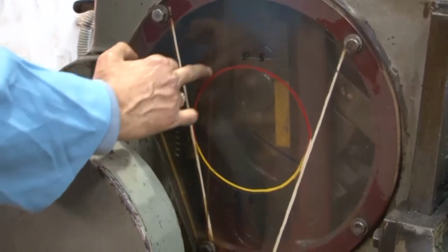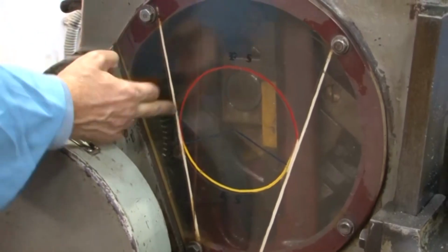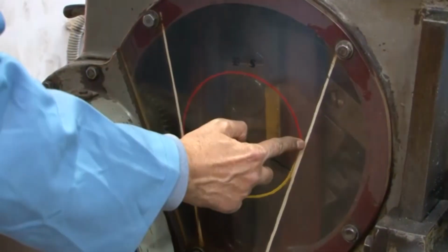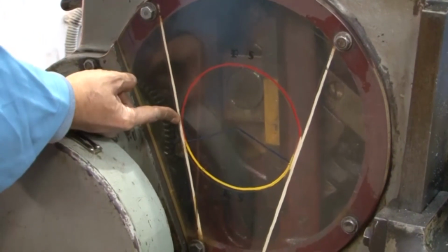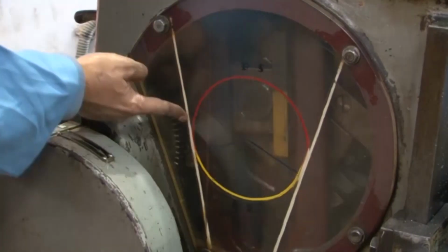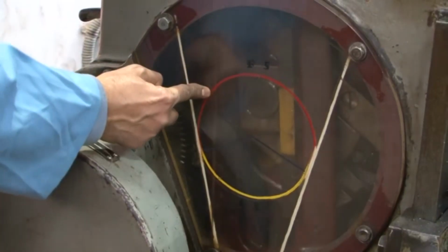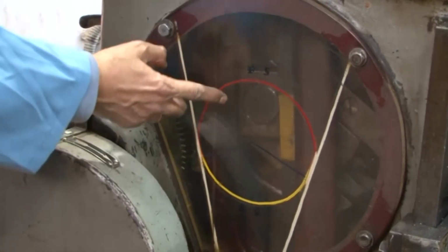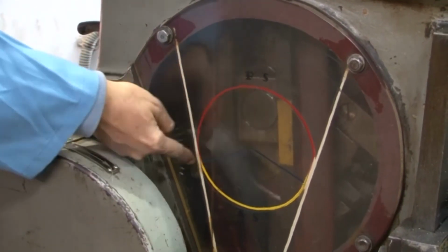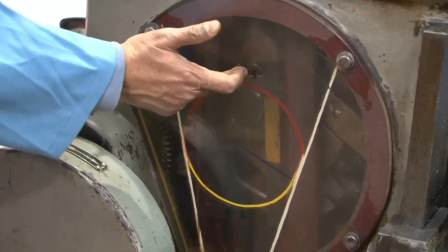So, here you can see that this is the forward motion and this is the backward motion, all right. So, when it goes like that, this is the forward motion when the tool will be removing material, and then from here to here it will come at a higher speed. So, the time taken for the tool to come from here to here will be less than the time taken for the tool to go from here to here, that is the forward stroke, and this ratio is the quick return. So, by changing the length of the arm, you can actually change the quick return, the speed.